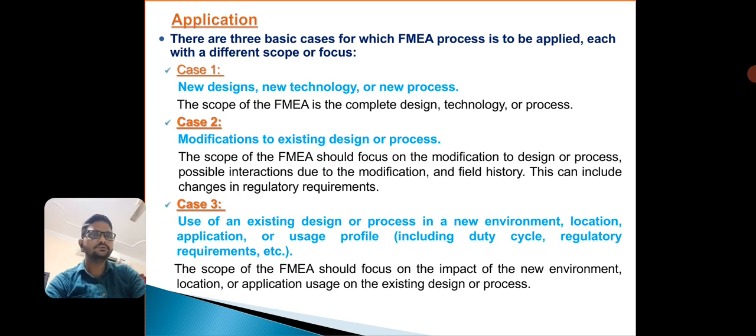Third one is use of an existing design or process in a new environment, location, application or user profile, including duty cycle and regulatory requirements, means government regulatory requirements. Any change in application, any change in location, any new environment, we need to modify our FMEA.